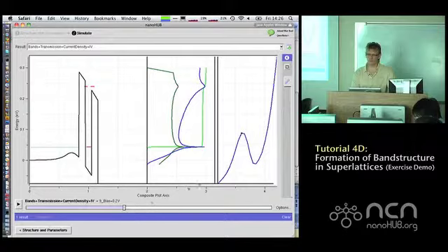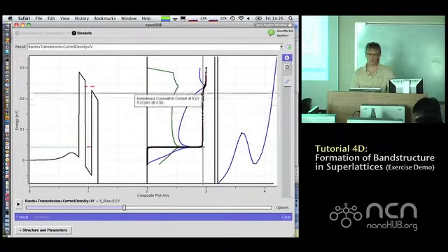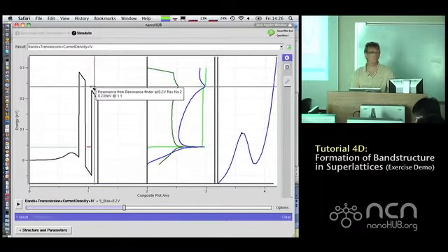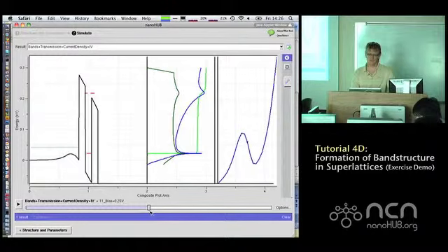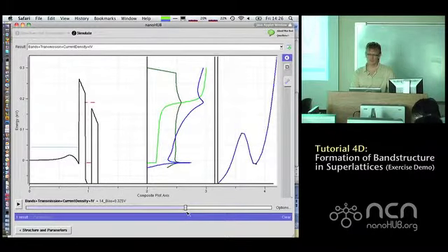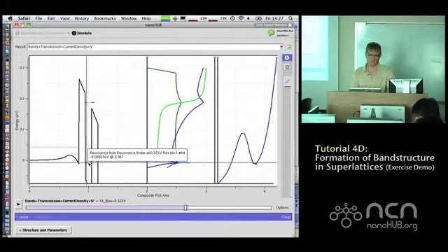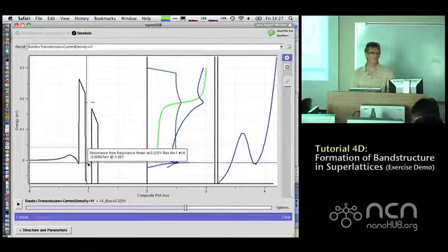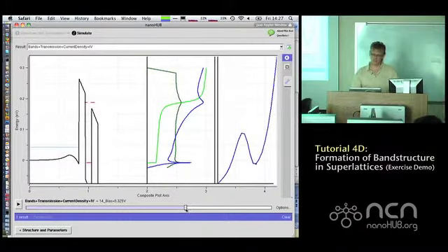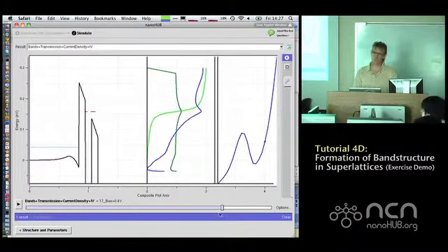So now we're at peak voltage right here. And even so, there's quite some current already flowing in the excited state that is up here. All right? And as you ramp the voltage further, you start to cut down on the current. And there's a little bit of current flowing still, and you can see it's basically aligning with this band edge here, okay? So by default, in this tool, we have turned on this relaxation in the reservoirs, okay?